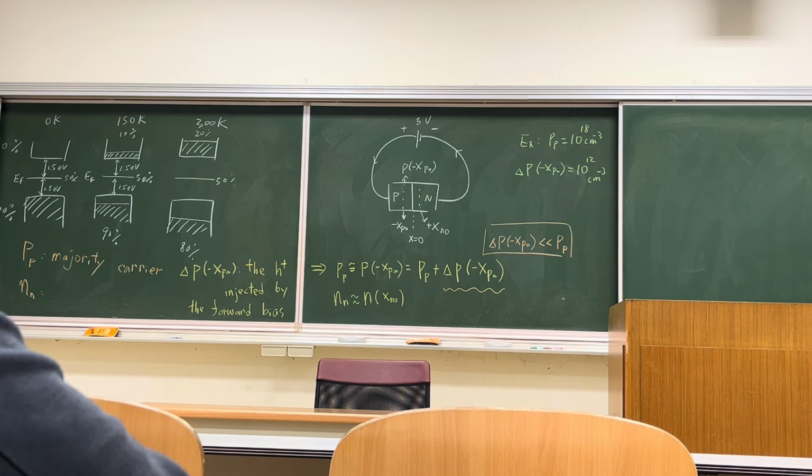How about the fourth one? That's super famous, so it has a special name, which is called the Shockley ideal approximation. Shockley is the name of a scientist, right? What did he say? He said the recombination in the diffusion region can be ignored, which means when electrons go into the diffusion region, they will not be recombined by the holes. Why? How can you assume there is no recombination between electrons and holes in the diffusion region? Why?